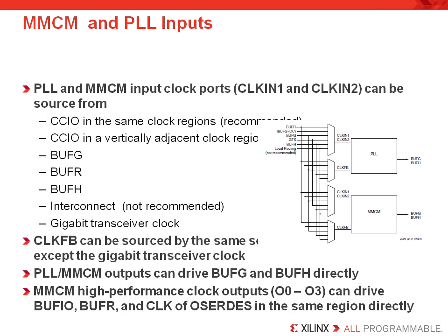Now, these connections are among the most common use models, so it's strongly recommended you consider using them. And we'll talk more about the other use cases of the MMCM and the PLL in the next recording. But the other thing I'll point out to you as well is to keep in mind that these selections are made automatically for you when you configure your clocking resources using the core generator. And we'll look at that later on in the next recording as well.